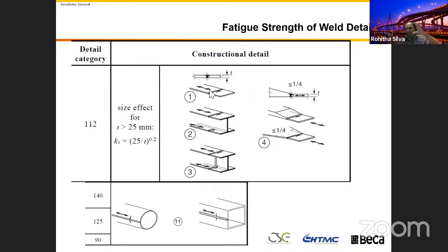So when you have this bridge, if you put a simply supported beam with the girder at the bottom, the tensile stress in the bottom flange will fluctuate because of the stress reversal, right? If we have a welding detail like this, corresponding to 2 million stress cycles, you can have a maximum stress range.